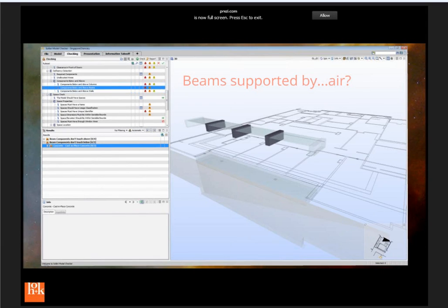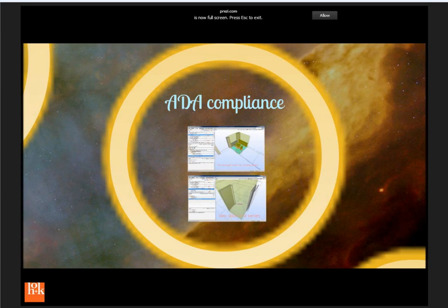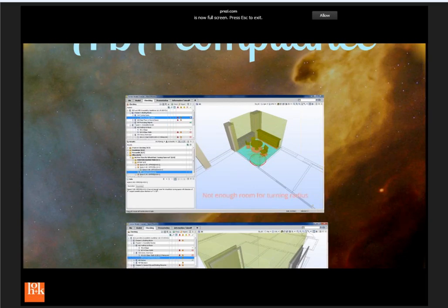And it goes through and finds all the different problems that you may have and stuff that you may have never seen before. Whether your structural opening slabs match the architectural openings of the slabs. Are the shafts lining up? Is there anything intruding into those shafts? It understands openings. These are the types of tests that are difficult to do in Navisworks that are fairly easy to do here. And this is why it's becoming, at least at HOK, more and more used every day. I mean, obviously Navisworks is ubiquitous, but this is a better tool, in my opinion.